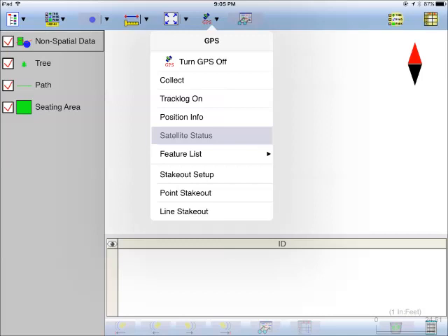After finding a desired location, you may stake it and store its coordinates. The accuracy of the stakeout will depend on the accuracy of the GPS receiver used. Keep in mind, though, that GPS elevation errors are usually twice or 3 times as large as the horizontal position errors.